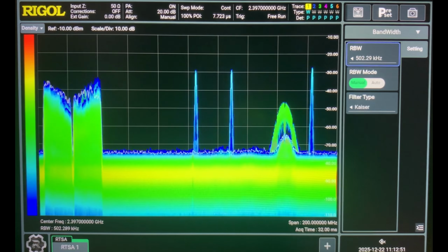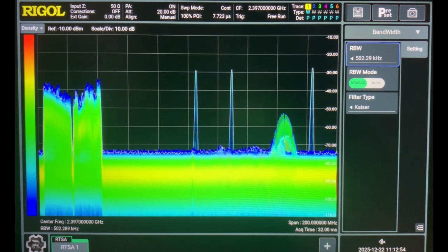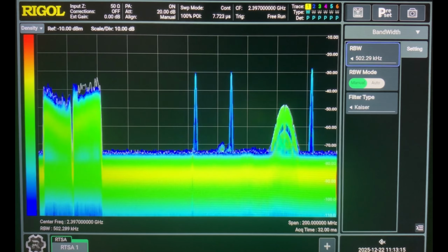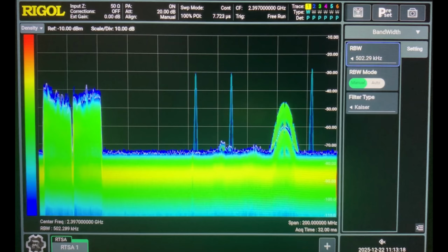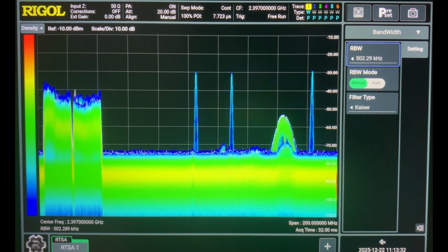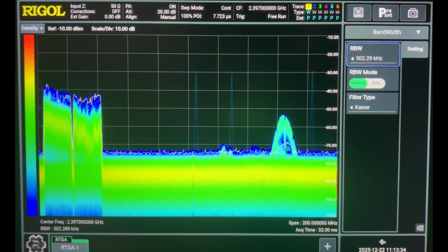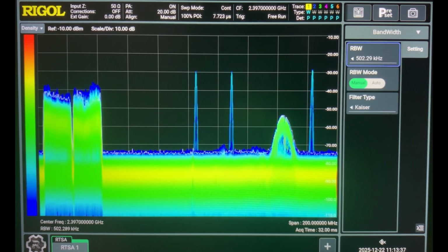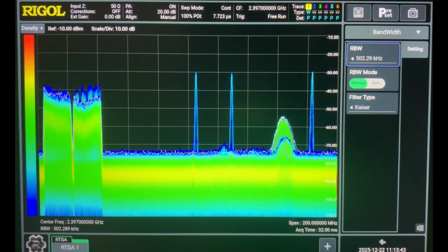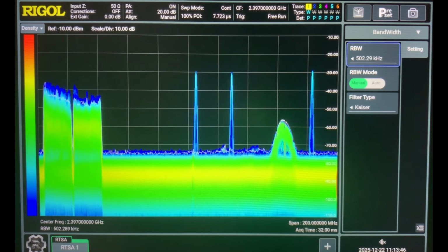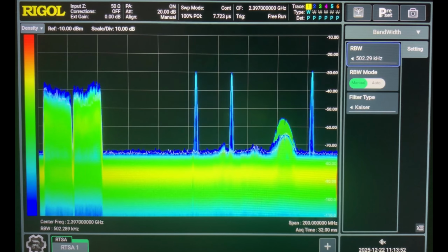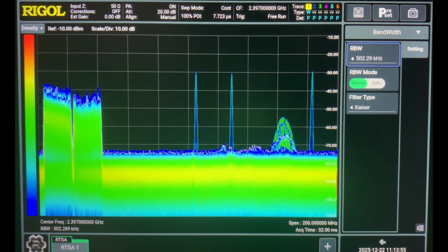Let me switch on the Bluetooth on one of my phones. You see the signal? On the other hand, FFT size controls frequency resolution. A large FFT gives more detail but uses more processing power. For beginners, start with the default setting. Reduce bandwidth if needed. Focus on seeing the signal, not perfect resolution.